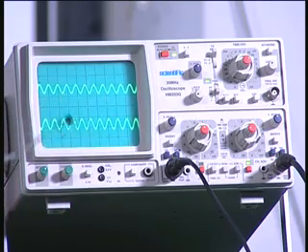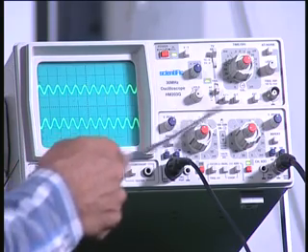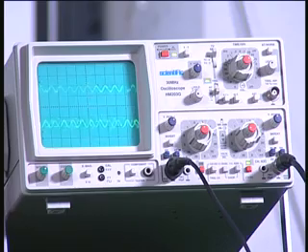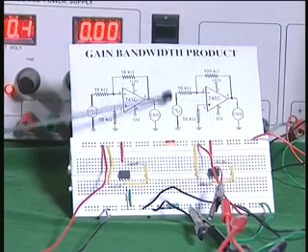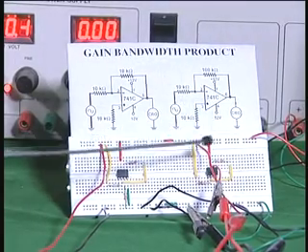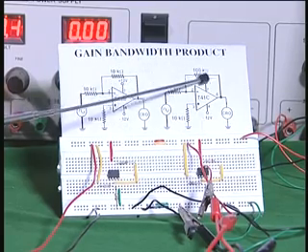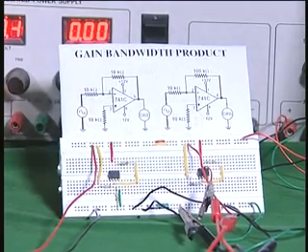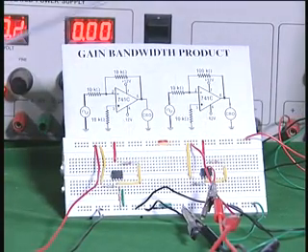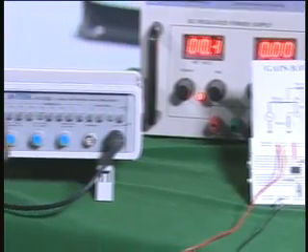The amplitude here is almost equal because the amplification factor using the knob has been kept 10 times, that takes care of the gain of 10, because in the feedback I have used 100k, and 100k divided by 10k gives me a factor of 10, that is the gain of this amplifier. Now the same amplifier is shown here, except that this resistance which was previously 10k I have changed to 100k. Now the 2 inputs are given as usual, and let me now vary the frequency and see how the amplitude is changing. So I am changing now in 10 kilo.